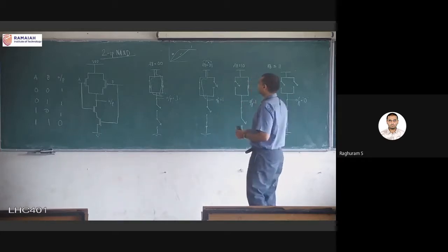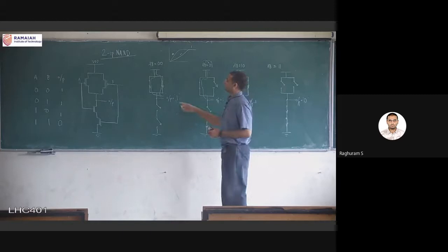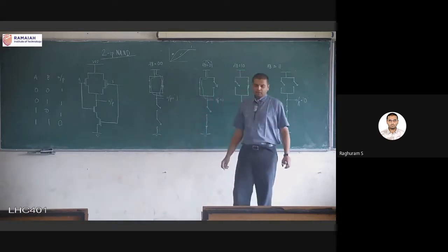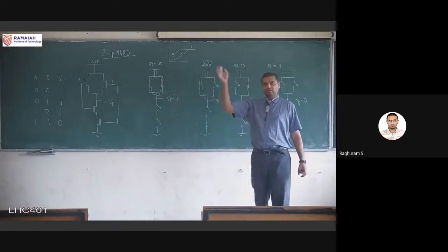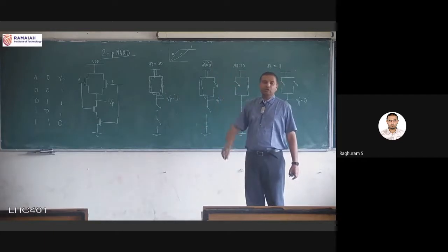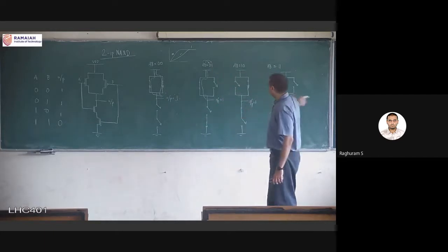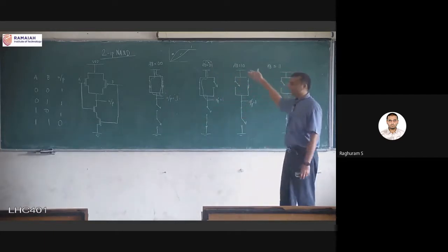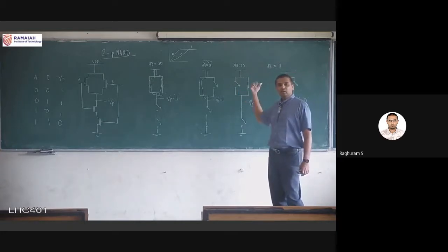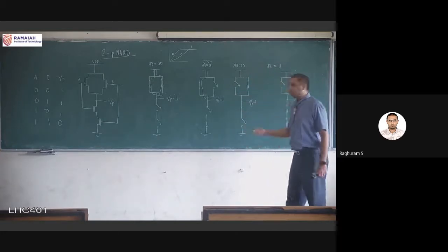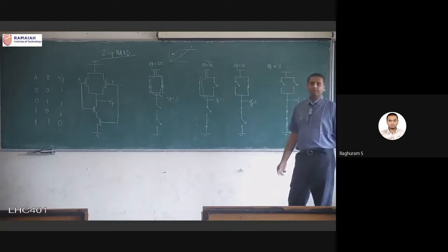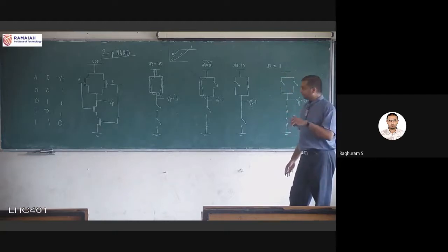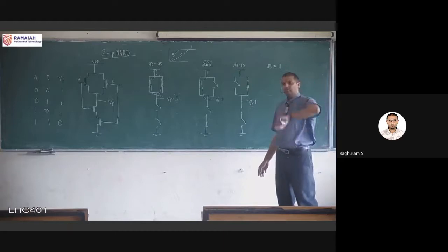Another thing is, we mentioned that the output is connected only to VDD or to ground. That is in all the three cases. First three cases, output is connected to VDD. The last case, output is connected to ground, but also there is no connection to VDD. So definitely the output is connected to only one, that is either VDD or to ground.